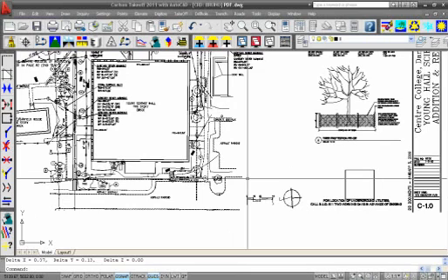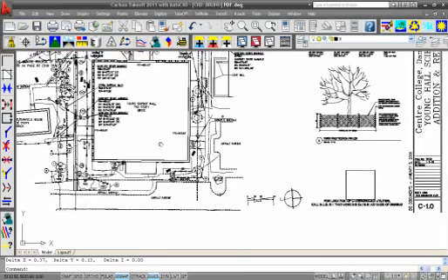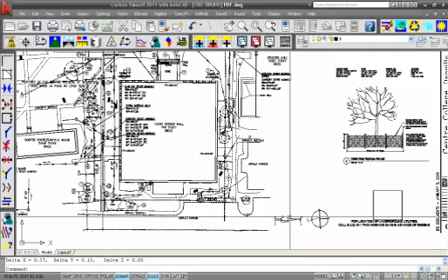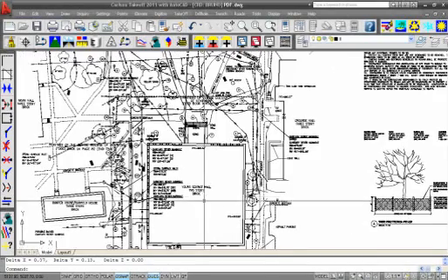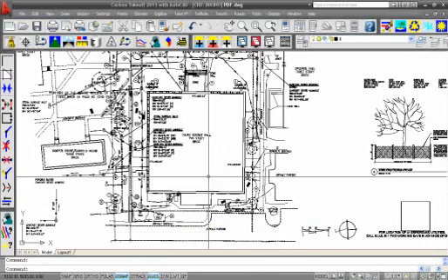Yeah, in terms of workflow, you typically would scale the drawing first. You can bring in a PDF, maybe do a drawing cleanup on it, but one of your first steps should be to scale the PDF so all the line work you create is true. You're not doing that after the fact. Yeah, so this is a step I could have done first when I brought it in, but I got excited with the different layers.